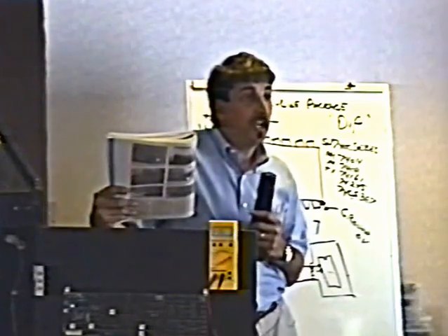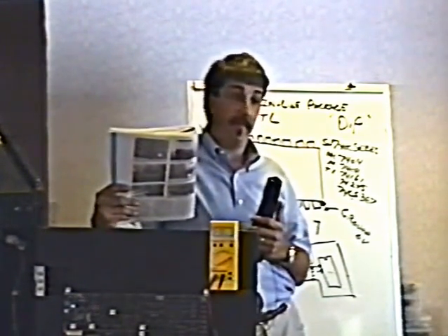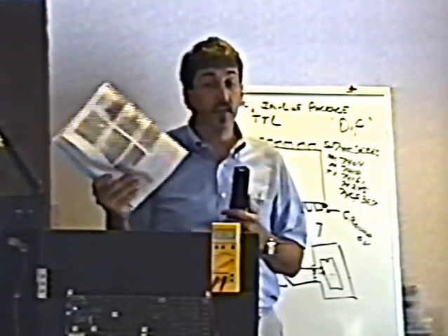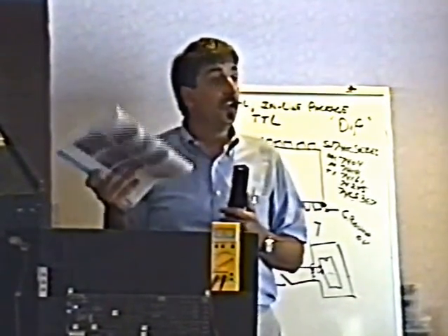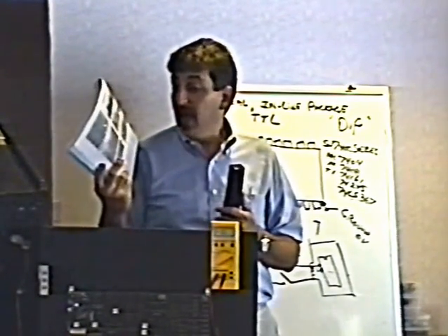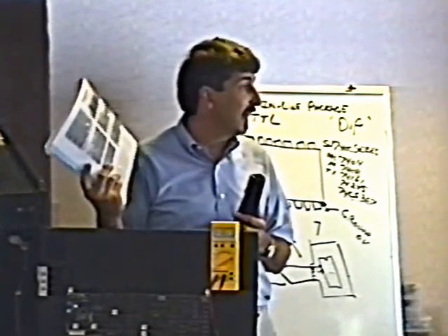Now, when I change a chip, it only takes 5 minutes, and you cannot tell that I've changed it. It looks perfect. Again, it's just a matter of practice. Soldering, especially changing chips, is a skill that takes a long time to develop. You really gotta sit down and try this. But by pulling out the pins one at a time, it makes your job a lot easier.